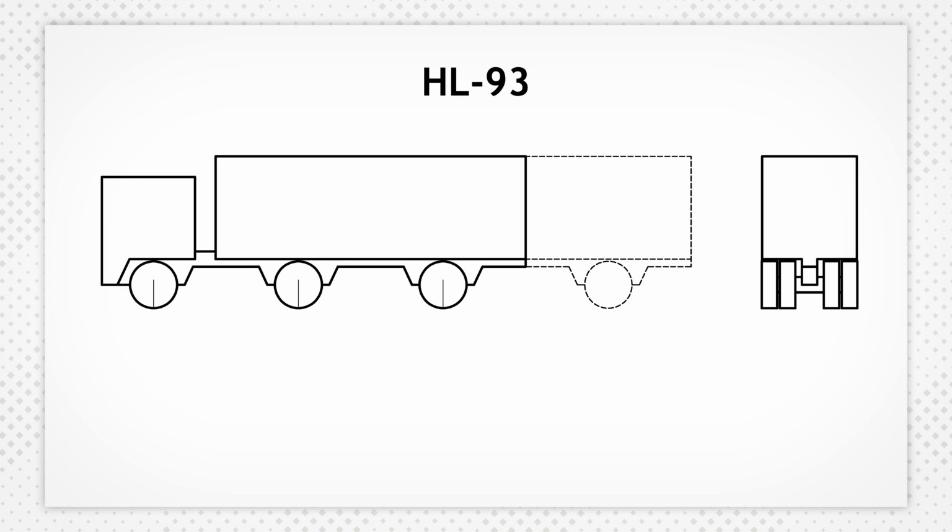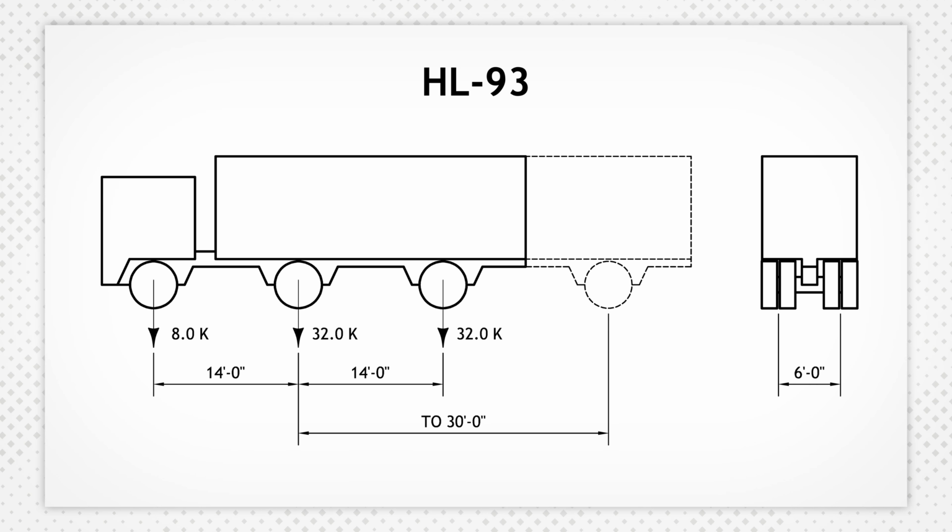In 1993, the Bridge Design Committee came up with what's called the Highway Loading 93. It's a combination of an HS20 truck, which is 40,000 pounds on part of it, and then it's got a concentrated load, and it's also got a distributed load. That was made to describe the loads bridges are facing, but it's a load that cannot be reverse engineered. It's not a truck. Vehicular live load is used in superstructure design.